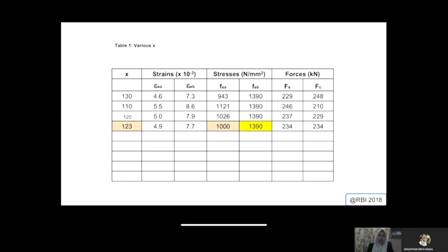All right, but you have to come to a point whereby when you calculate your forces, the steel force and also the concrete force will be the same. When you get it the same, then you can conclude your x optimum for your section is equal to 133. So in general you have to do trial and error. That's why normally we don't really calculate this manually.